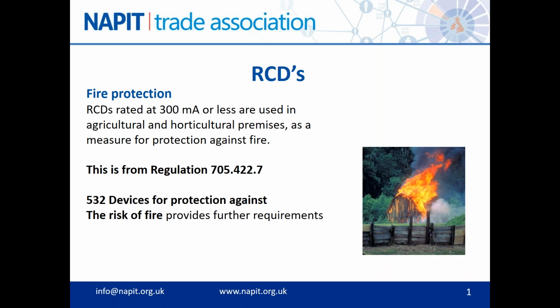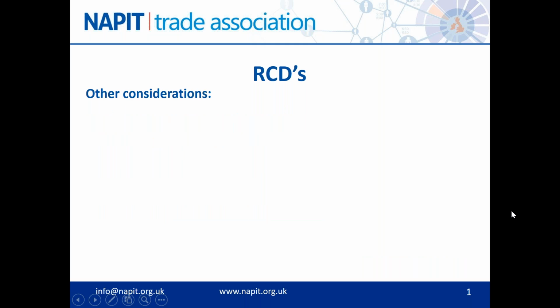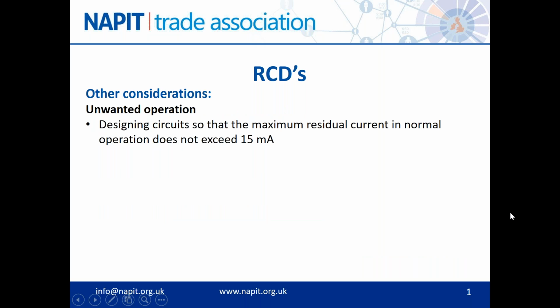RCDs for fire protection are installed in wooden barns, in stables, in agricultural and horticultural places where you get a lot of hay and dust and dry materials during the summer. Even thatched properties. The design of a thatched property may include in the specification that you should be putting some type of fire protection RCD up front. There are, of course, other considerations to think of when we're talking about RCDs. RCDs will operate